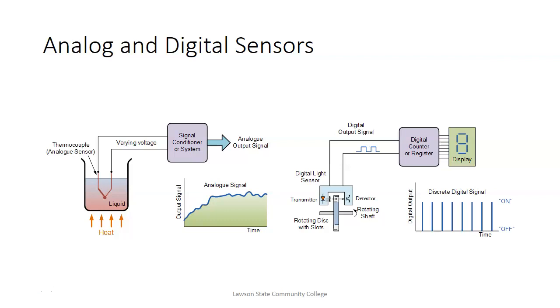Thermocouples are used in your oven. So when you set 375 degrees on your temperature, thermocouple, these are analog devices, and these are actually measuring the temperature for you, so they're really accurate. If you've got a gas water heater outside, odds are it's got a thermocouple on the pilot light to control the main valve. So analog sensors give us a varying output, so you can understand this is very, very desirable.